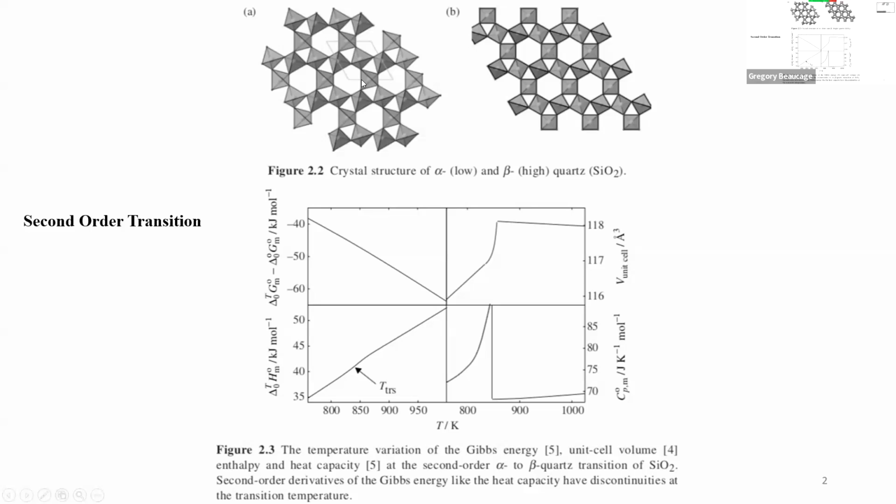But if you look at the change in volume with temperature, the slope of it changes at the glass transition. If you melt a crystal and do diffraction, the liquid has an amorphous halo, and the crystal has a bunch of spikes in it. So there's a dramatic change in the structure. It goes from totally ordered to disordered, right? Whereas in a second order transition, they look the same above and below. The only thing that's changing is the rate of change of the thing, right?